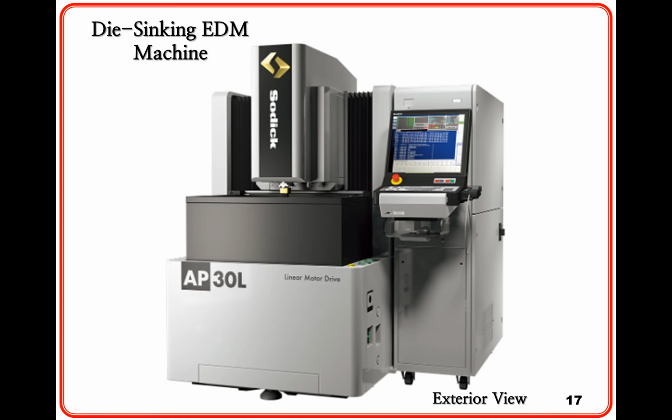An impulse voltage of approximately 60 to 300 volts is applied between the electrode and the workpiece. When the gap between them is reduced to approximately 5 to 50 micrometers, dielectric breakdown occurs at a point between microscopic surface irregularities of the electrode and the workpiece.